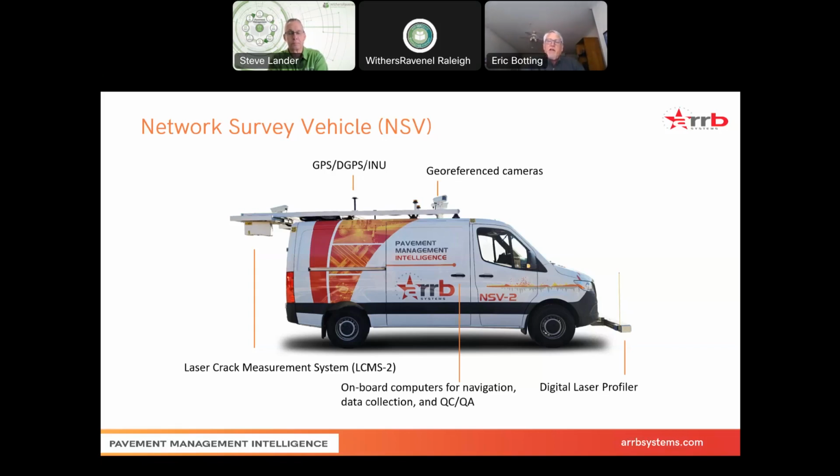So the bounce test is actually what they do. It starts out and it measures the distance from the laser to the pavement. Okay, so now let's put a bounce to it. You put a little block under it, a known value, a millimeter or centimeter, and then you bounce the vehicle. When it stops, you measure it with the block to make sure those measurements are still accurate. Those are done every day, to test that the accelerometers and lasers are working together.